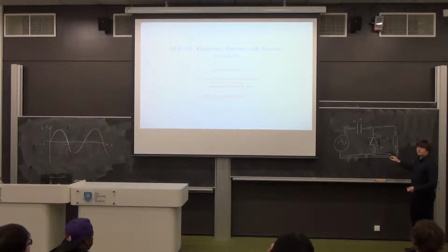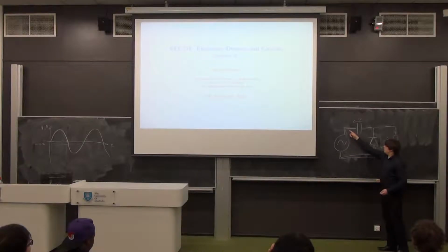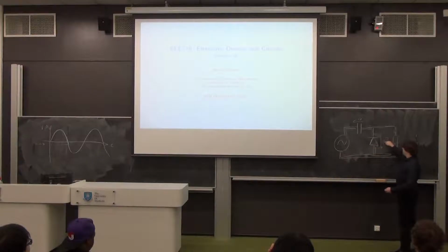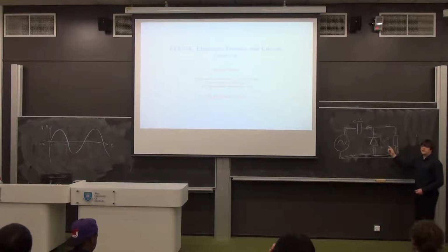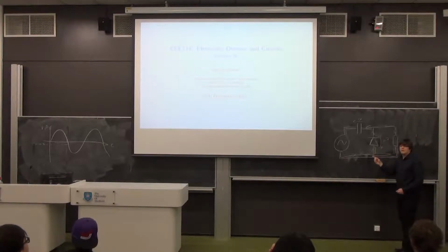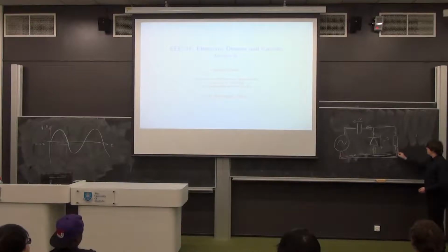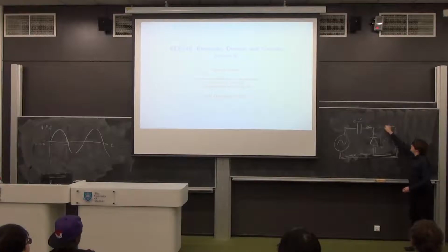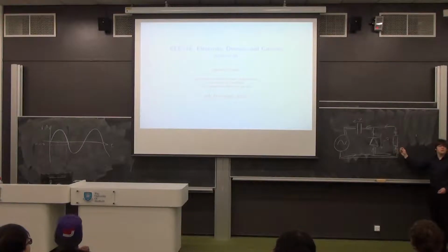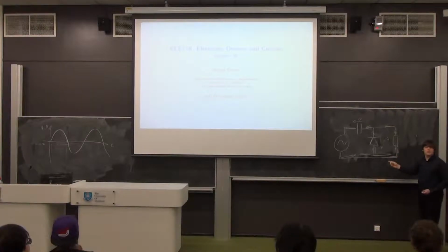And if you could press play on the diagram, next thing that happens is this voltage gets a bit smaller compared to this one. So this gets a bit bigger and a current flows out of here through the diode and onto this plate of this capacitor. And this current is large. It will easily fill that capacitor quickly, certainly in the time that's available before anything interesting happens thereafter. The resistor still isn't up to much, but there is a little current that flows through it which assists this charging, but it's negligible in comparison to the current that flows through the diode.